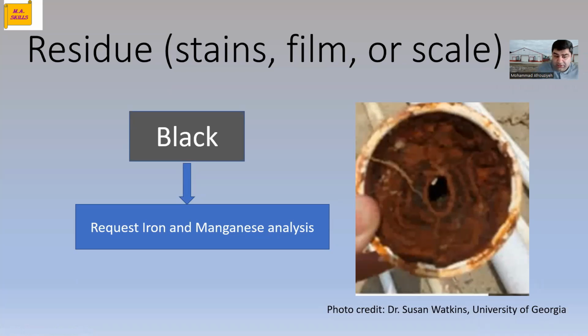And if their levels are high in your water, then you need to oxidize them using chlorine, chlorine dioxide, or ozone, and then filter it with properly sized mechanical filtration. Or specifically, as I talked about, if your water manganese is high, you can use, again, the oxidation method or reverse osmosis, ion exchange system, or aeration and filtration to get rid of manganese.